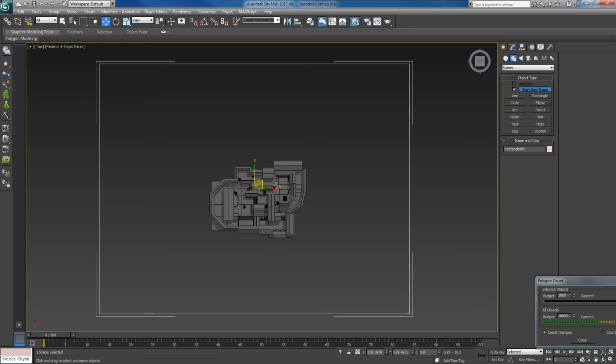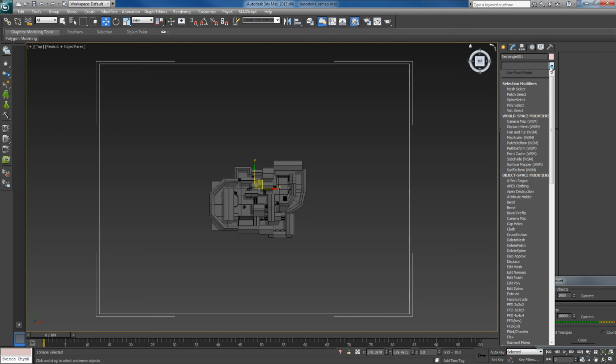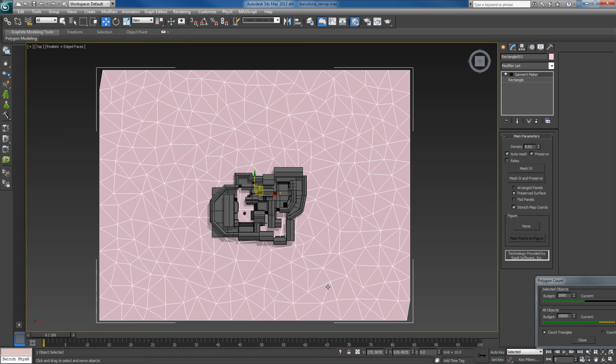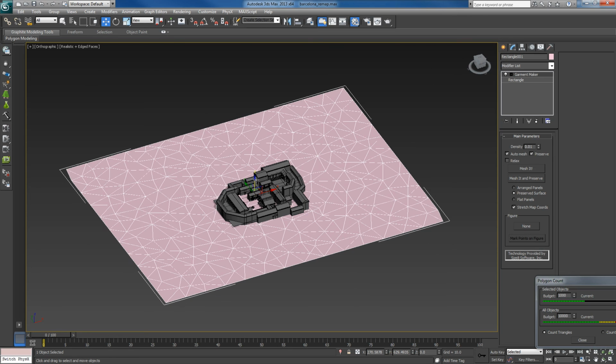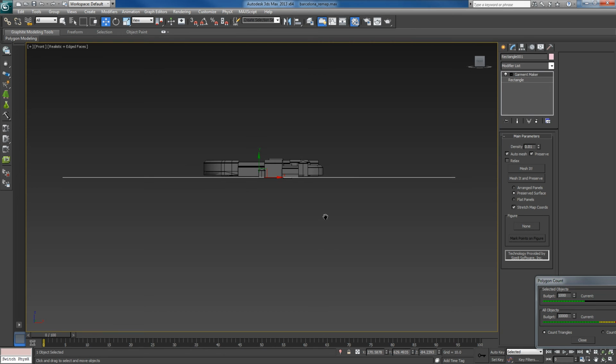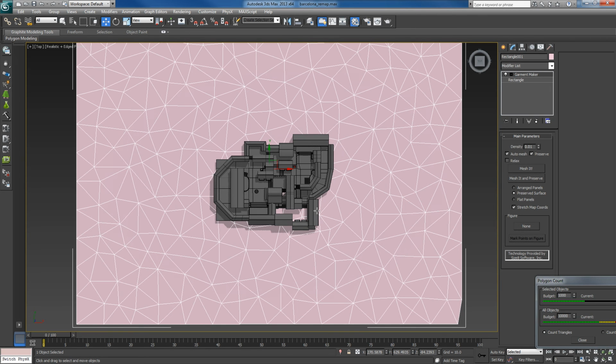So to create a cloth as part of the cloth simulation feature that's available in 3ds Max, we simply draw out a rectangle and we use a modifier that's available to us called Garment Maker, which is right down here. And as we apply that to the surface, you can obviously see that the topology is immediately different than the topology that we had with a surface suitable for hard body surfaces. So right away, it's not difficult to see how this would perform better as a flag compared to its hard body version in polygons at a decreased value.